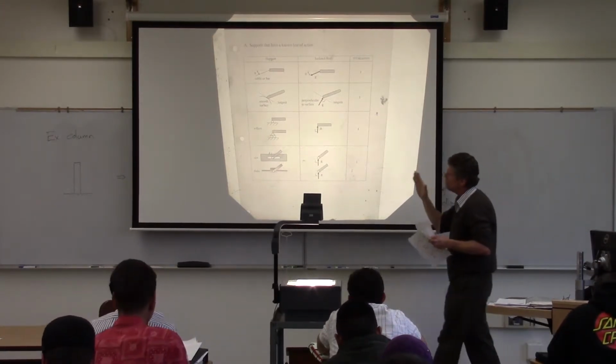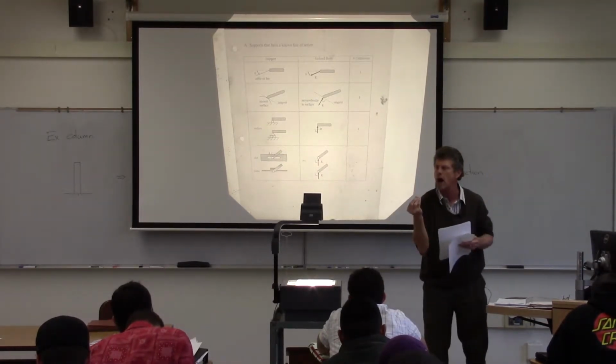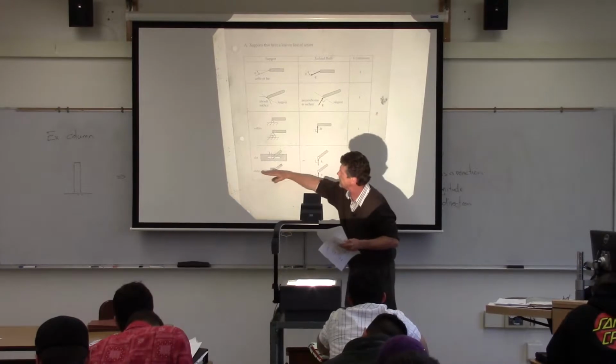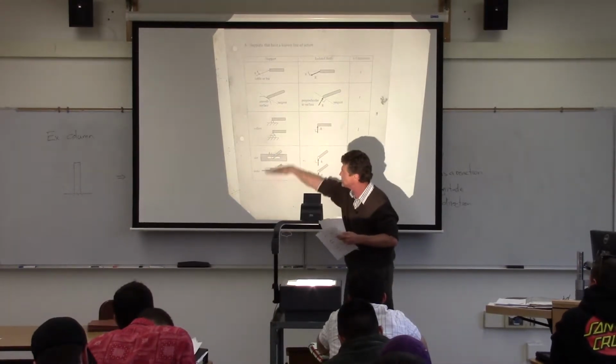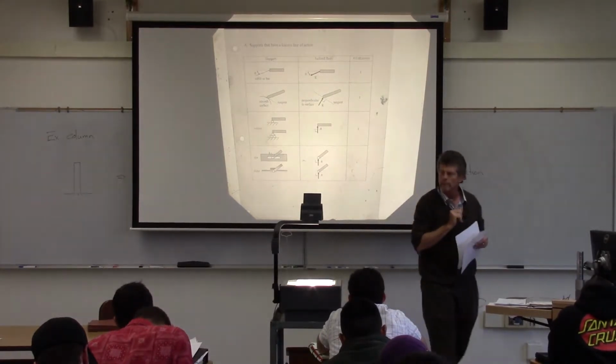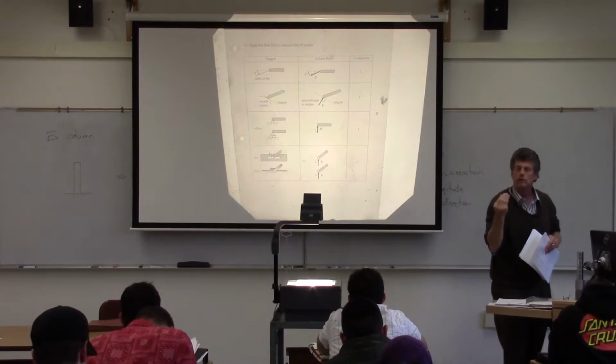So again, the only force that's acting on that is going to be perpendicular to the surface that it's contacted to. So in this particular case, it's a slider, it's a bar. The slot is not going to allow the bar to go that way. One unknown, just the magnitude. We know its direction.